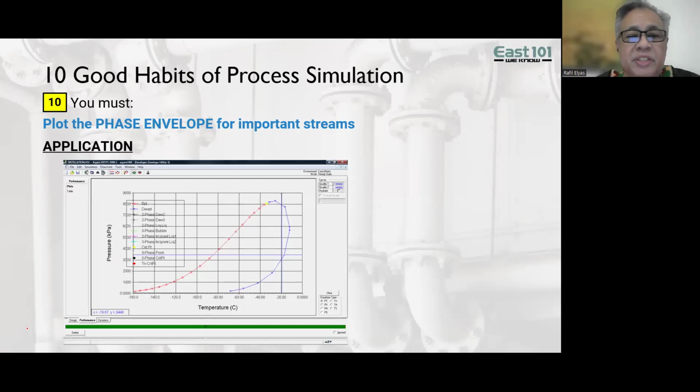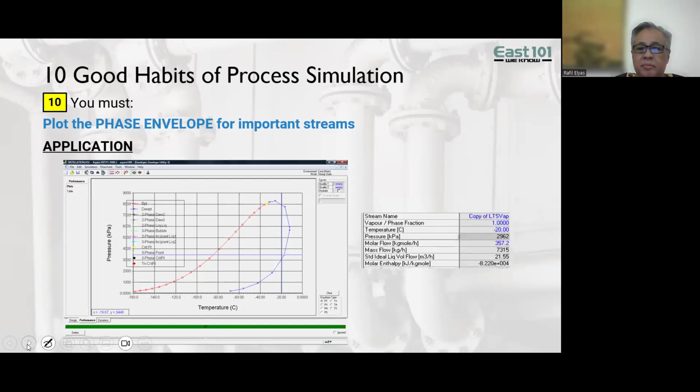So I go to the phase envelope attachment thing and I generate the phase envelope and I get this. And I get this number, which is about 29 bar, which makes sense. Yeah, at minus 20 degrees Celsius. But I realize when I look at this diagram that I actually have two solutions. So in this case, I've got this fat or bulging region, and that's a retrograde region.